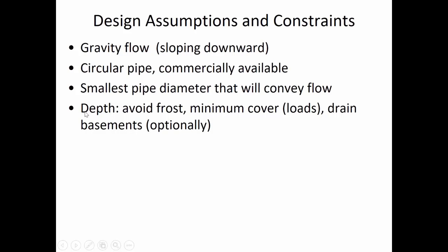Burying the pipe a certain depth below the ground surface will help to keep it warm and avoid the water inside the pipe from freezing, because nothing reduces pipe capacity more than a big gigantic piece of ice inside of your pipe network. And so we have to bury it deep enough for that, and also if it's buried too close to the surface, then cars that are passing over the pipe can transmit the load into the pipe rather than into the soil cover that's over it.